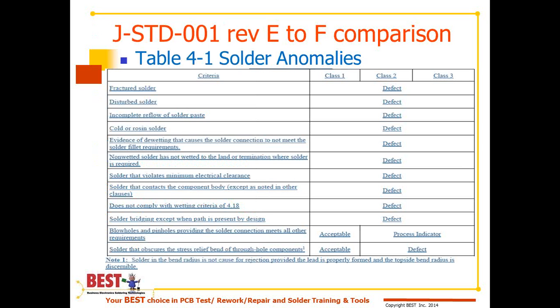And they've added the note 1 to identify what they mean by that, in that the solder in the stress bend is not a cause for rejection, provided that the lead is properly formed, and you can still see the top side radius of the bend.